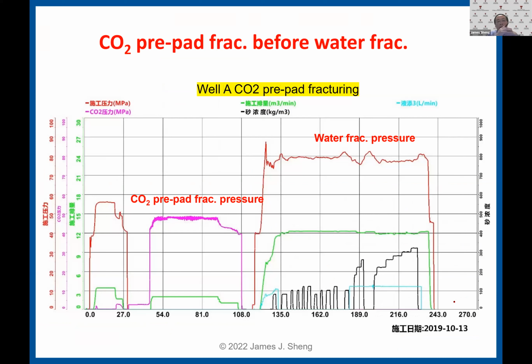Next, I'm going to talk about CO2 fracturing. Probably you have heard about it; especially in recent years, people are more interested in using CO2 to fracture. Why? Because CO2 is a high energy, highly compressible fluid. During fracturing, you flood the reservoir, and this high pressurized CO2 will provide energy during the flowback.